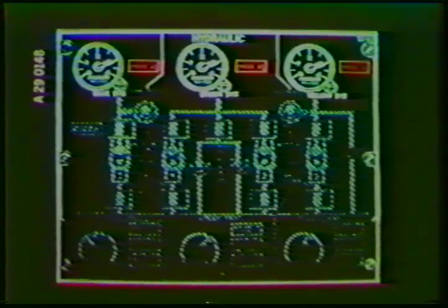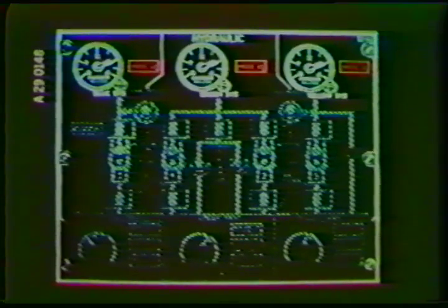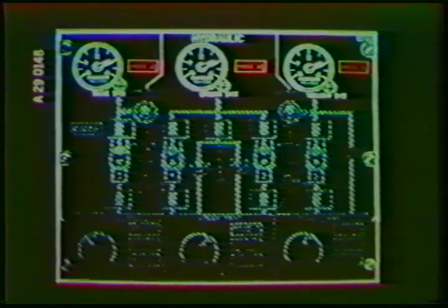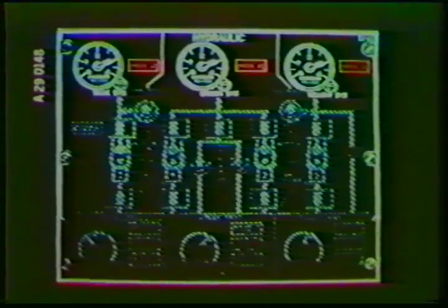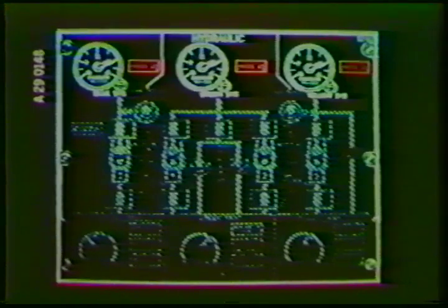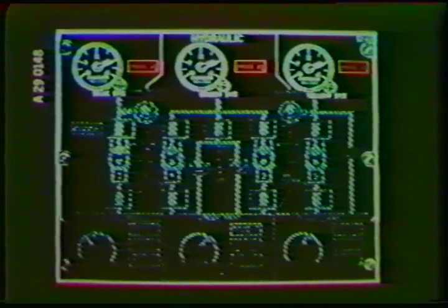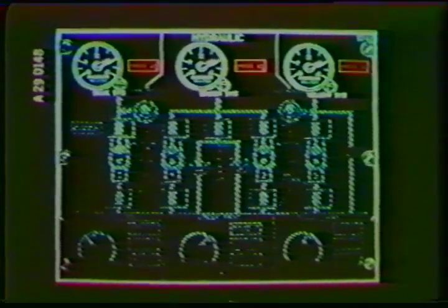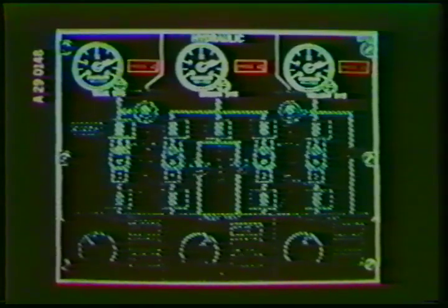Three pressure gauges located at the top of the control module register the pressure being produced in each system. In addition, 3 amber low-pressure warning lights monitor pressure. A low-pressure warning light will illuminate if a system's pressure drops to less than 1,450 psi.